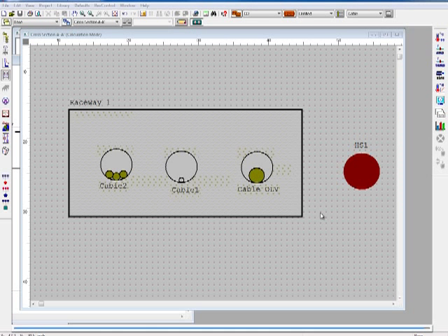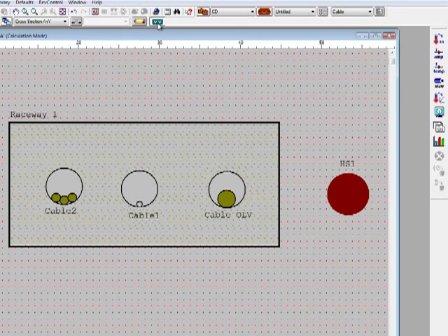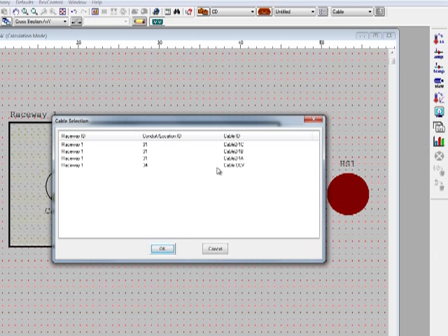You can perform transient temperature analysis for an underground raceway system. You need to go to the calculation mode and then simply click on this button to perform the transient temperature calculation. By running this analysis, ETAP will generate the plots. So you can click on this button to open the plot for the cable that you have in the system.